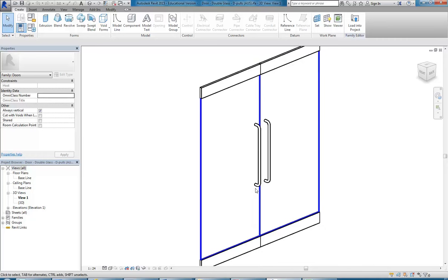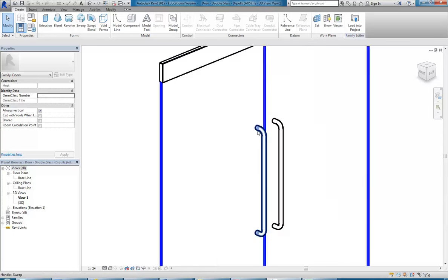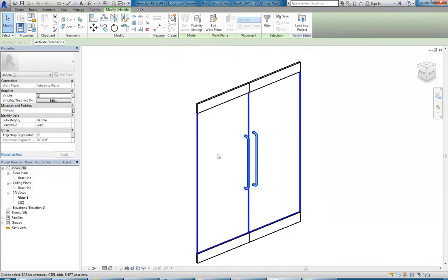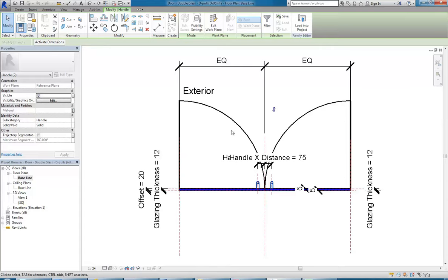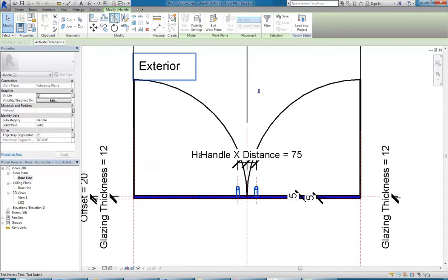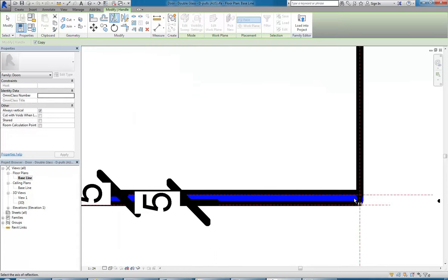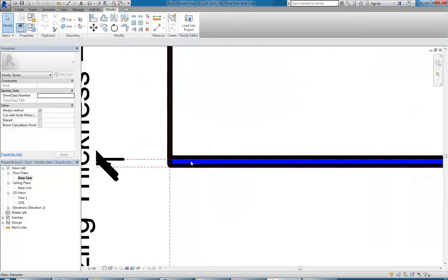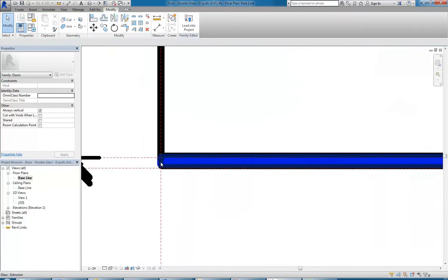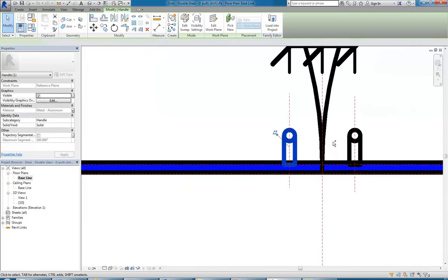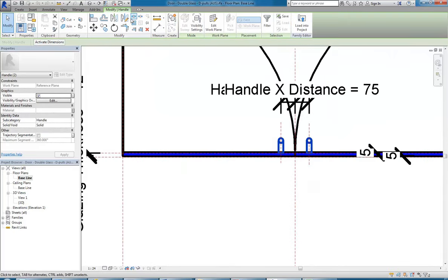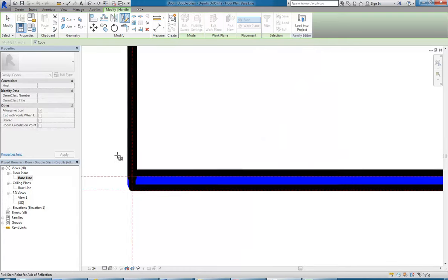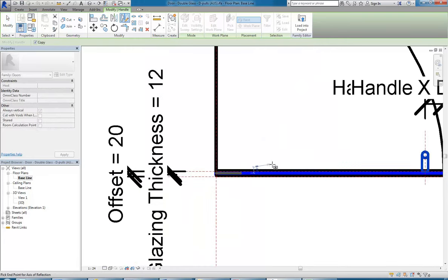And so I'd probably want these door handles to be on both sides. So that's a simple thing I can adjust just by selecting them both in 3D view. Can then go to the plan view and then just flip them using mirror and try to get the centre line, which of course they don't have set up, so I'll cancel that. Or sorry, I'll just use mirror, draw axis, using the midpoint of the glass.